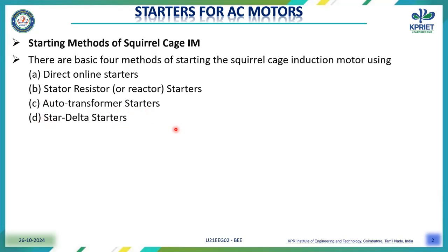Why is a starter required for an induction motor? At the time of starting, the induction motor takes a starting current around 5 to 10 times more than the normal or actual running current. So in order to reduce or control the starting current, we have to use a device called the starter. That is why a starter is required for an induction motor.